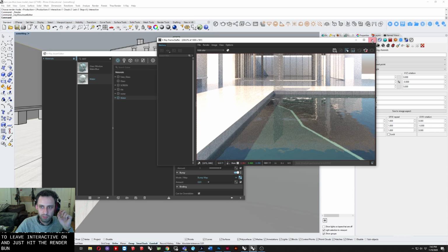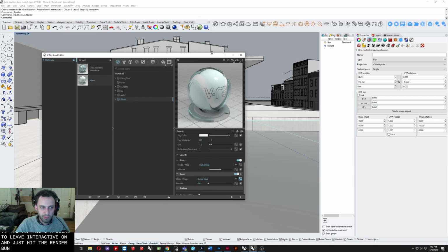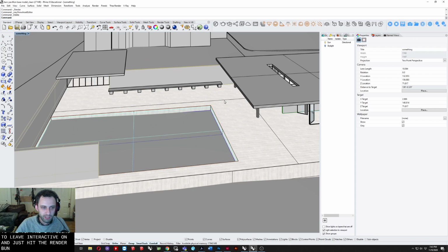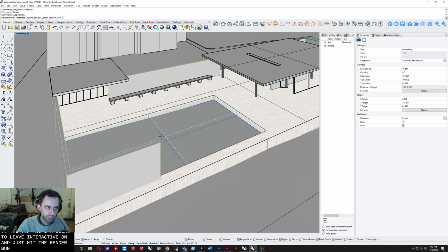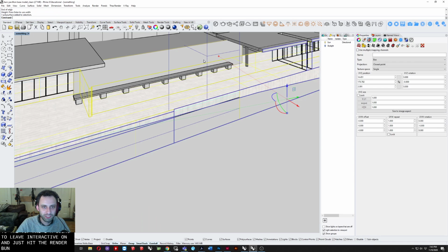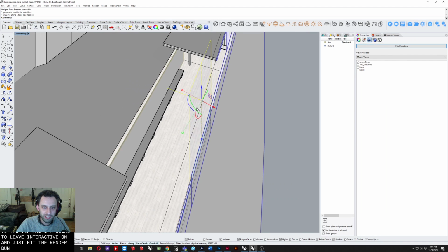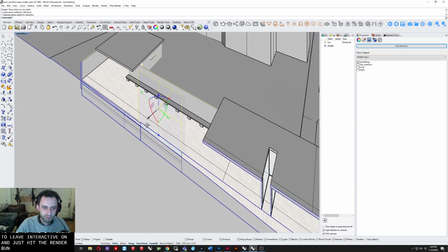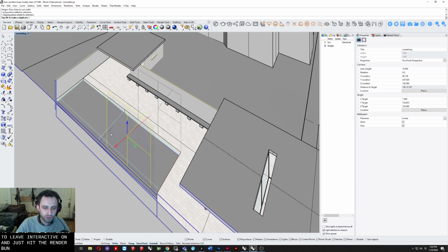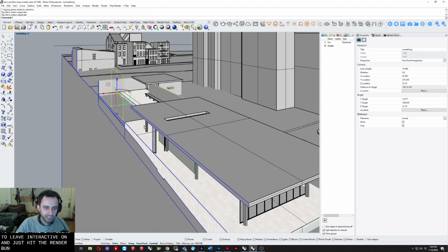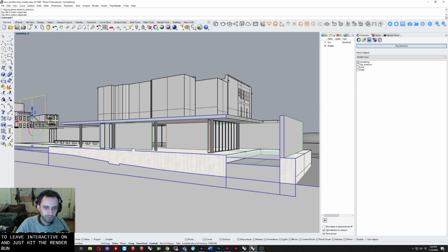So pause this. Something that V-Ray can do that Thea can't, which I think is a really useful thing, is when doing a clipping plane. Both programs can do clipping planes and render them properly, which is really fantastic. It's actually a relatively new feature in comparison to these rendering engines. In the past, you would actually have to go in and do a Boolean operation to remove half the building and delete it in order to render it properly, which always was a big hassle. So the fact that it handles clipping planes now is pretty great.